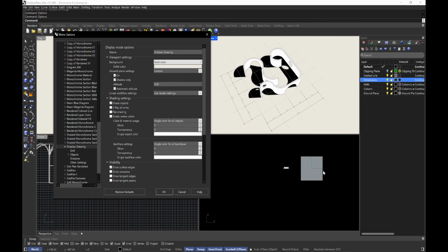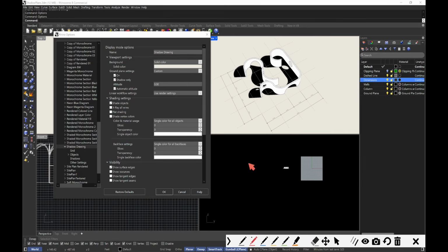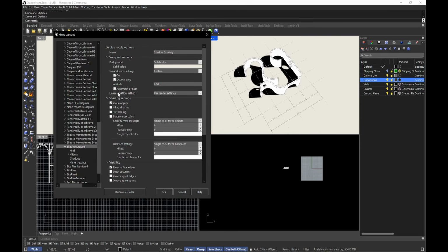So like in your elevation view right now, because everything is on the 0, 0 point, my ground plane is on the 0, 0 point. But let's say my model went into the negative space, like the model had a basement. Then the ground plane is going to be at the lowest point like that, if you have it checked on automatic. So if you don't have it checked, you can set it at 0, 0 or wherever you like, and then the ground plane will be here. So it's a matter of preference. Right now I have it at automatic.